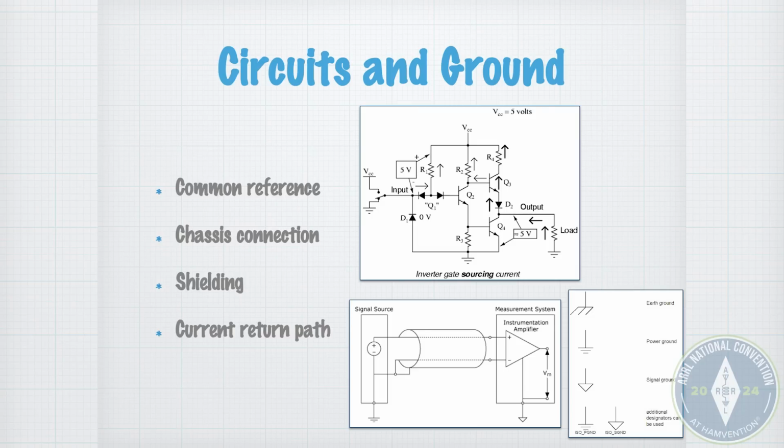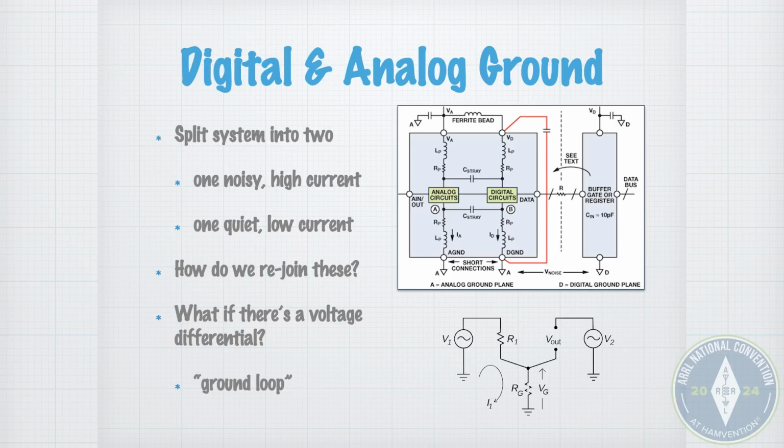And then we have digital and analog ground. If you've ever done any mixed signal designs, you see that there is one ground where you hook all the digital circuits up and they have a lot of current, and so the ground is, in theory, bouncing around. I mean, there's a problem right there, right? The ground is bouncing around. And then there's the analog one, which is, in theory, not bouncing around so much.